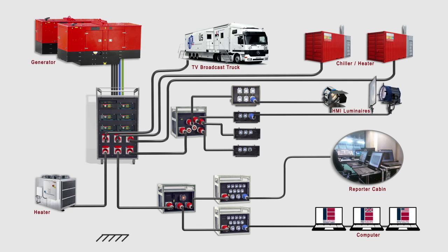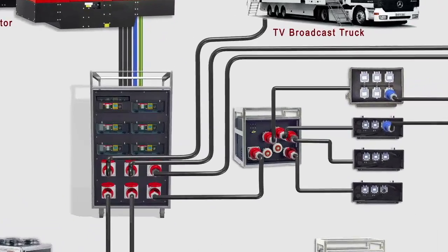Let's now take a look at fault current. Fault current is current that flows back to ground outside the actual live conductors due to an insulation fault. If, for example, a person comes in direct contact with a live conductor, a ground fault current occurs. The connected RCD detects this fault current and immediately interrupts the circuit. Unlike the mainly capacitive leakage currents, fault currents of this kind usually have a high resistive component.